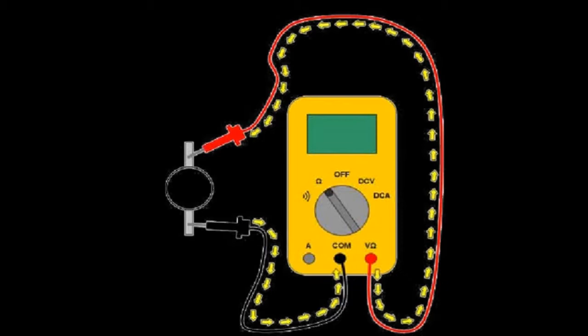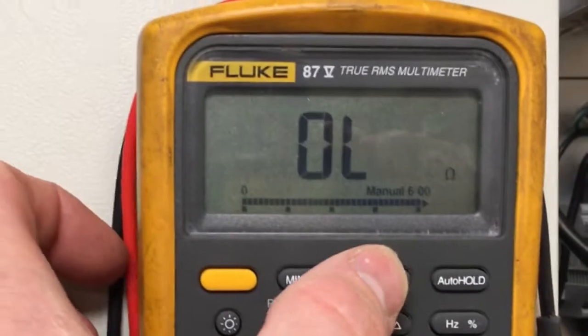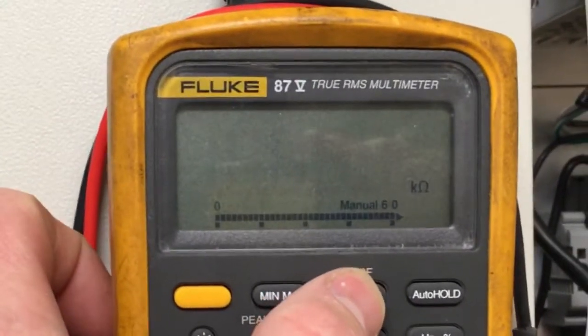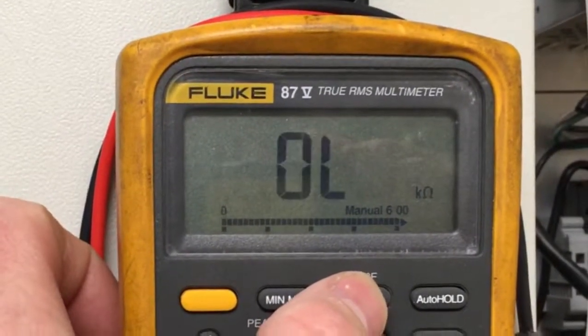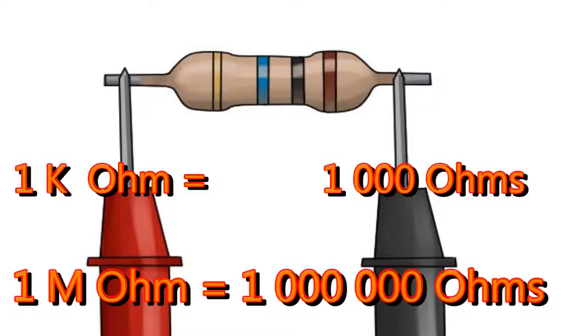When this option is selected, a small amount of current is passed through the circuit to calculate resistance. This value defaults to auto range mode and allows for a manual range to be selected. The circuit being measured must always be free of voltage for this measurement to be accurate. The unit of measure in this mode can be one of 3 units: ohms, kiloohms, and megohms.